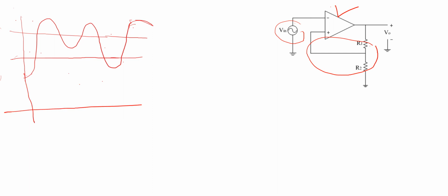From the input side we can see that we have given two threshold values. First one is the lower threshold value and second one is the higher threshold value or upper threshold value. Since we have given an inverting input, suppose initially output will be high for the low input. So our output will be high until when? Until the input crosses the upper threshold value.